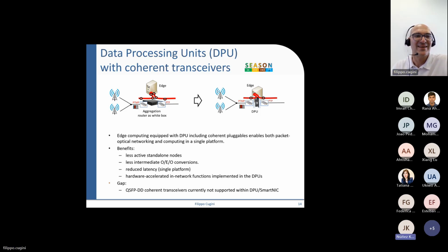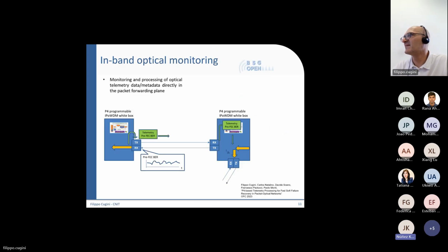Thank you, Filippo. I have one question related to the telemetry of the transceivers, in this case for the coherent pluggables. Something I am quite interested in is the pre-FEC and the noise variance that you can have, because right now a lot of these pluggables are working with shaping, which produces a really weird type of noise. So usually, is the pre-FEC that you are defining something fixed, or does it change depending on the requirements of the network?